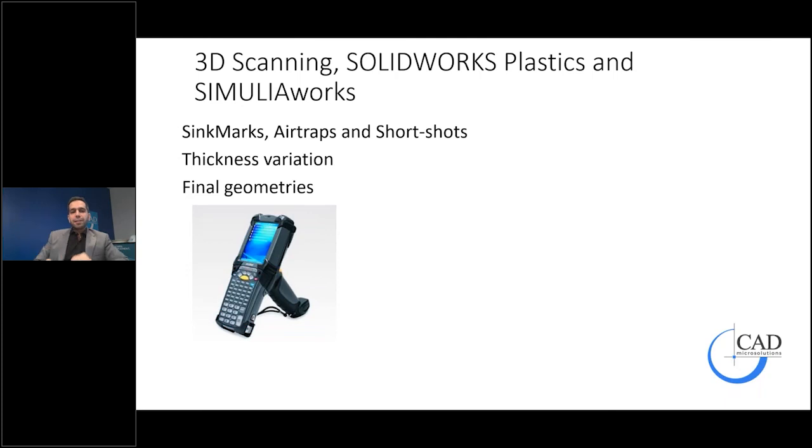During all of these analyses that we do in real life, let's say drop test or thermal or vibration, the product doesn't care what was in the CAD. It cares what comes out of manufacturing. That's why we have our 3D scanning and metrology platform, GOM, the best one within our company and our team. We can 3D scan the parts that are critical, and then use the geometry as manufactured, not as designed, and bring it into our drop test analysis, vibration analysis, and all of that.